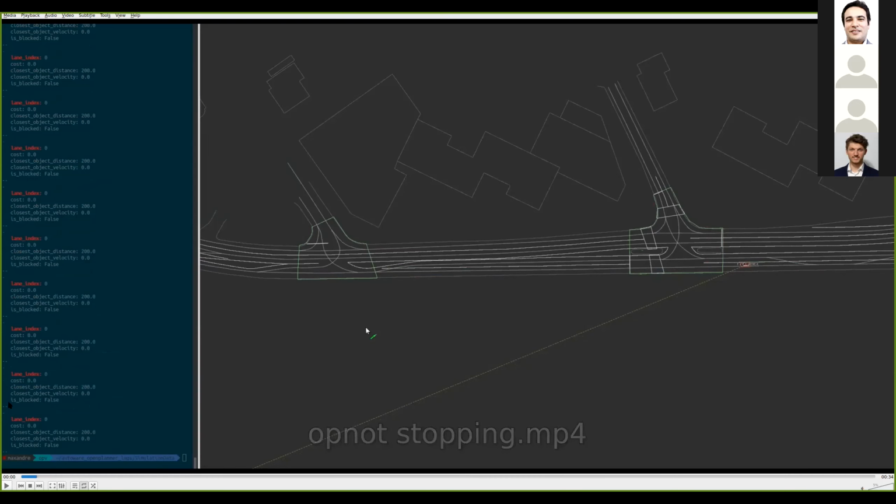It was just out of the box, really. Maybe you should just check the parameters, or the deceleration and acceleration factors, because this stopping velocity depends on those: the additional stopping distance, acceleration, and deceleration. Okay.